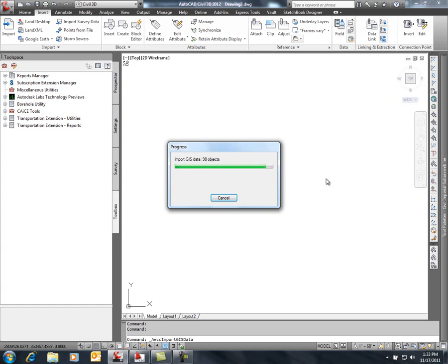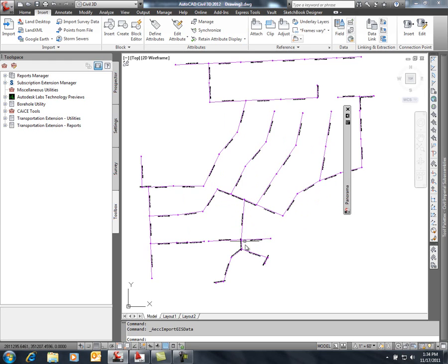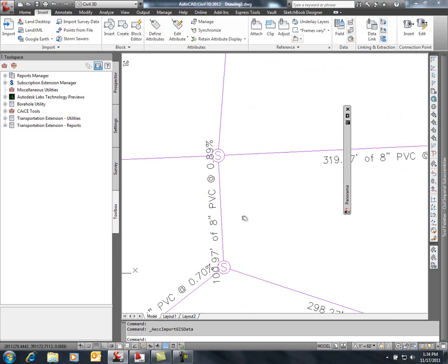Now, as it creates this in Civil 3D, it's reading those attribute values, and it's building not a pipe run that we would think of in Land Desktop, because Land Desktop would only give us a run of data from maybe an upstream to a downstream. As far as laterals, those wouldn't necessarily be considered. In Civil 3D, it will work with a true pipe network. So what we wind up with for our resulting pipes is an actual network of the entire system.